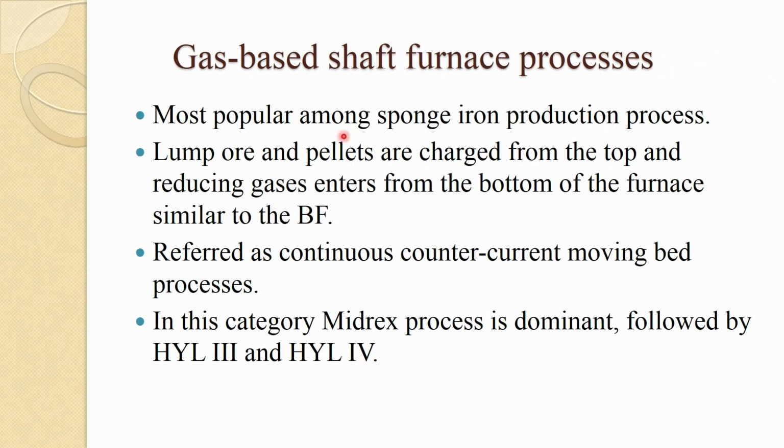Most popular among sponge iron production processes is this gas based one, where lump ore and pellets are charged from the top and reducing gases enter from the bottom of the furnace, similar to the blast furnace, referred to as continuous counter current moving bed processes.